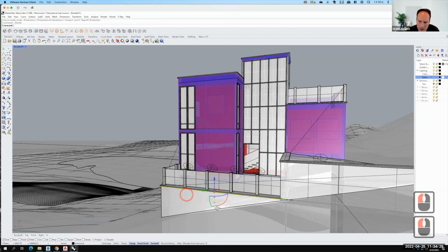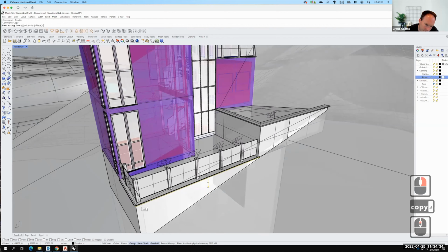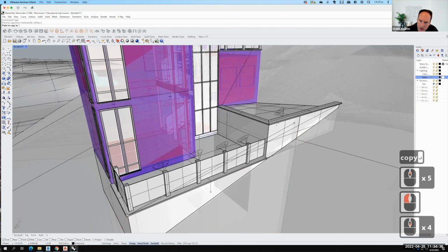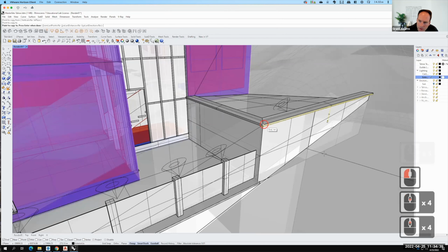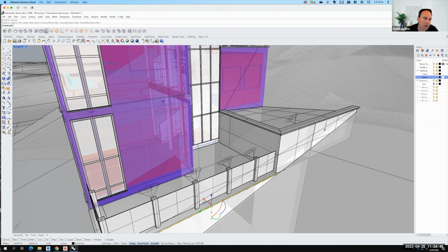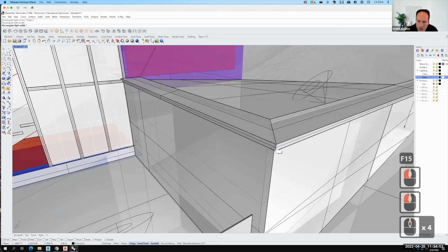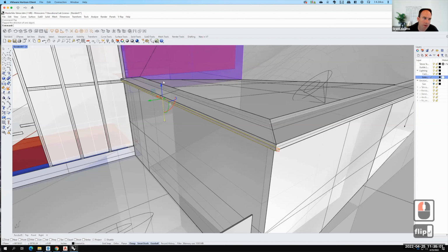So I could take that one that I just created and copy it, and we could drop it up on this one. There it is. So now I'm washing both of those. And maybe I want one more in here. This one I'd have to create. So we go into my rectangular light, and we go from there to there. And this one's pointing the wrong direction, so let's make sure we flip it. I'll type flip, and that'll cause the arrow to be pointing down.